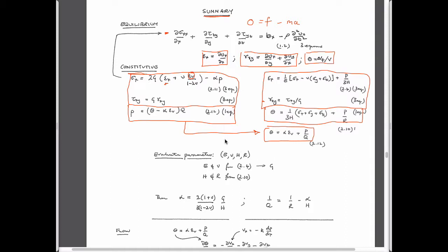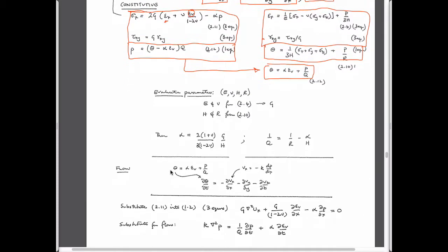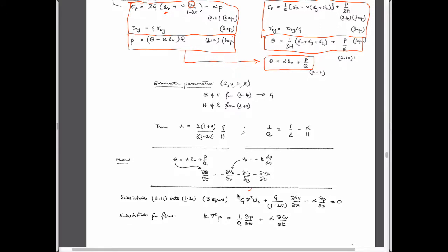So once we have those constitutive relationships, we can put them into the equilibrium equation. Once we have the equilibrium equation, we modify a few things, and we come out with a Navier equation, which is just a fancy way of saying the equilibrium equation with constitutive equations embedded in it. And it now includes the dependent variables that we have for our system, which are displacements x, y, and z, and fluid pressures. And so we'll have 4 degrees of freedom in a 3-dimensional system. So that's the solid part.